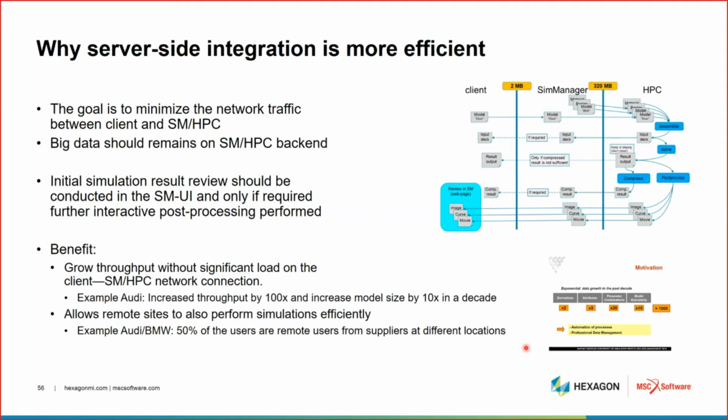For, in my case, the aircraft, we've got lots of configurations of loads and whether we've got stores on the wings or not, or what the deployment is for movable surfaces, etc. Out of that, you get your analysis results, which are the starting point to generate the internal loads on structures. And then from there, you're looking to do some downstream analysis to do the detailed check on individual components to generate the reserve factors for an aircraft. Are we looking at things which have got a serious risk or not?